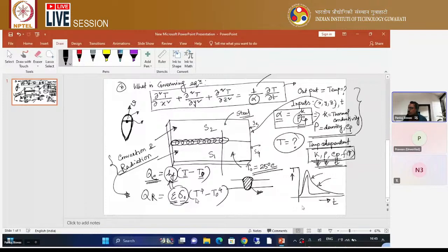it is better to use it for the conventional welding processes, like submerged arc welding, MIG welding, TIG welding, plasma arc welding. These are all very conventional arc welding processes. Generally, you can use this type of double ellipse heat source model with them.